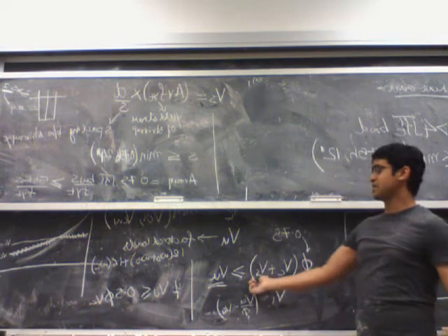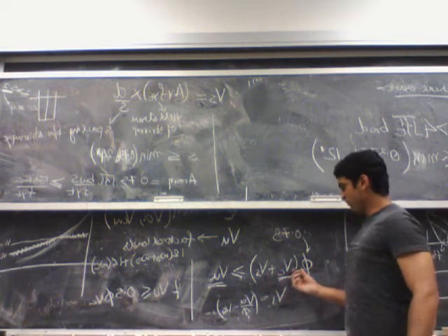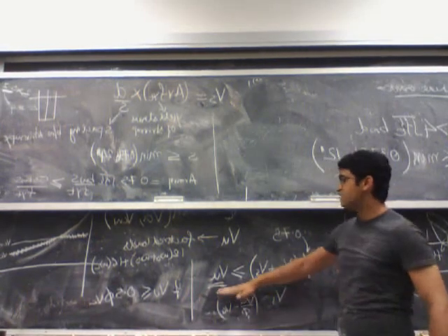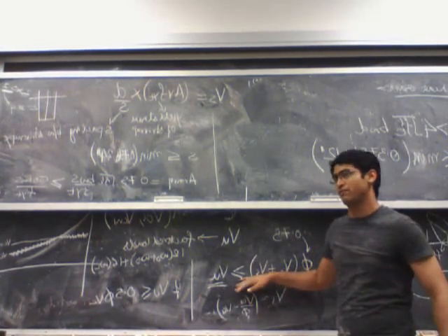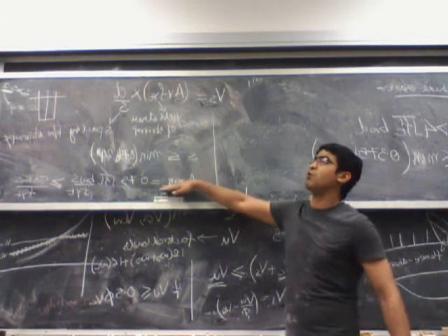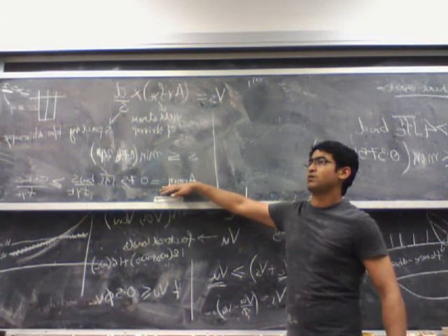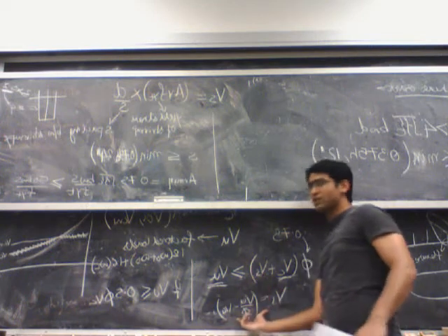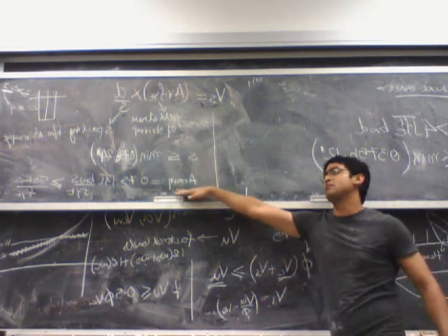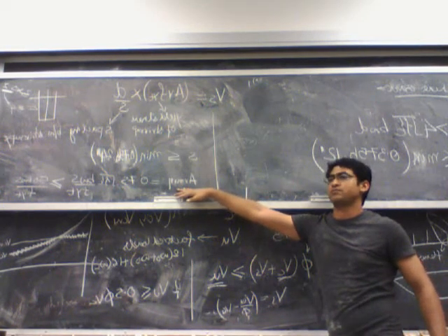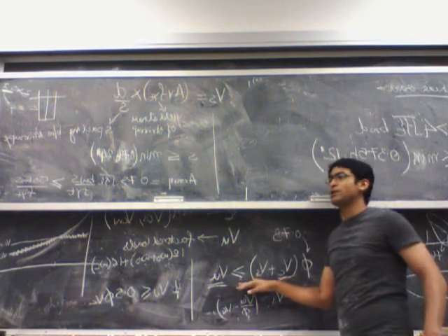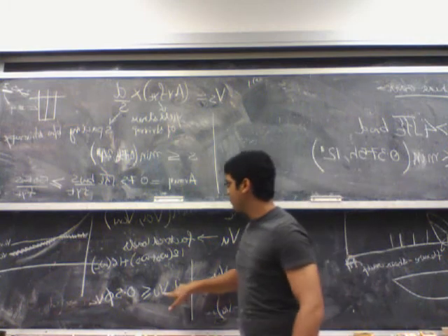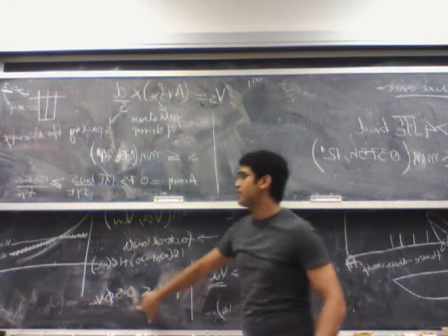But what ACI says is, if your phi times VC is greater than VU, that is, if VS from this formula comes out to be negative, still you go ahead and provide the minimum required. So if Vs comes out to be negative from this formula, you still go ahead and provide the minimum required stirrups, even though based on the formula you don't need anything. Only and only if your VU is less than 0.5 times VC.